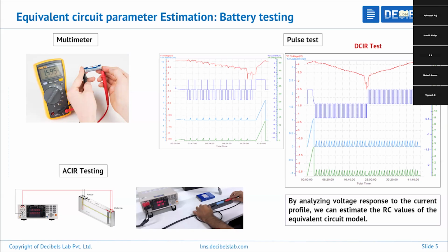From a fully charged battery to the lower voltage limit of your voltage window, you discharge the battery through pulses, not continuously. If you go continuously, it is like a static capacity test. So with variation of your pulses, you go through the full discharge of the battery and look at what the voltage response is. Those voltage responses you again need to check for your parameter calculations.